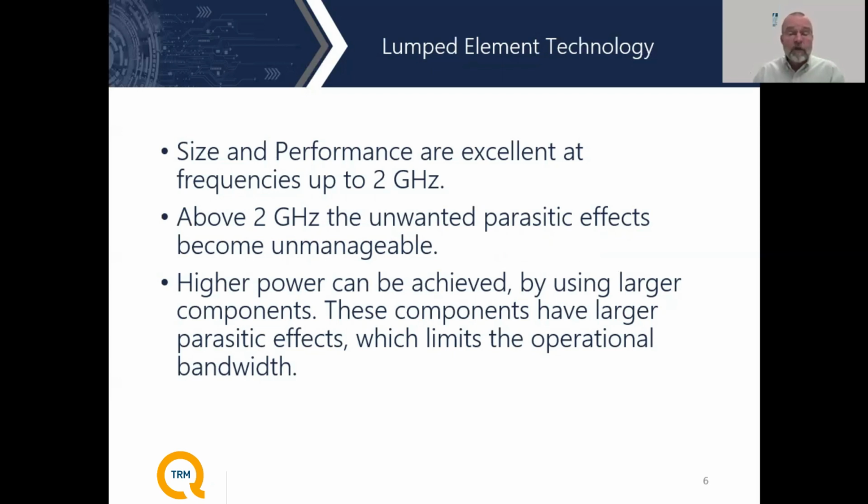An interesting thing of note here is that you can achieve very high power handling using ferrite technology. What happens though is when you get higher in power, you physically need to get larger beads to dissipate the heat. And when that happens, the capacitance of those longer wires starts to react more with each other, plus the stray inductance of those wires becomes more unmanageable as those beads and capacitors get larger and larger. So you're starting with the same very broadband basic network, but because the parasitics of those larger transformers are higher, you have reduced bandwidths.